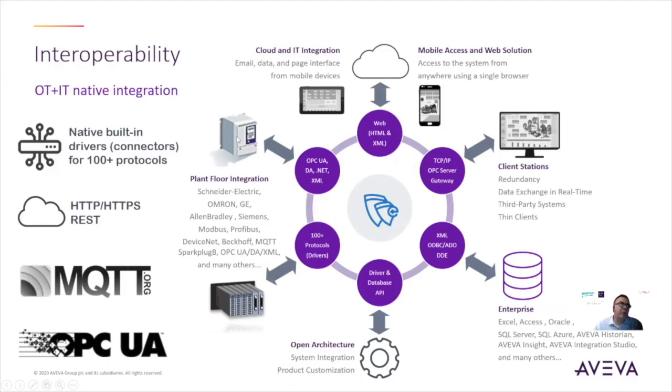So if we're a server, we can get to, if we're a client, we can get to third-party servers and connect to other devices. Maybe we don't have a driver for a particular device, or maybe a particular feature that you need in a driver is there, or manufacturer supplied it. So we can get to that again with either OPC DA or UA.